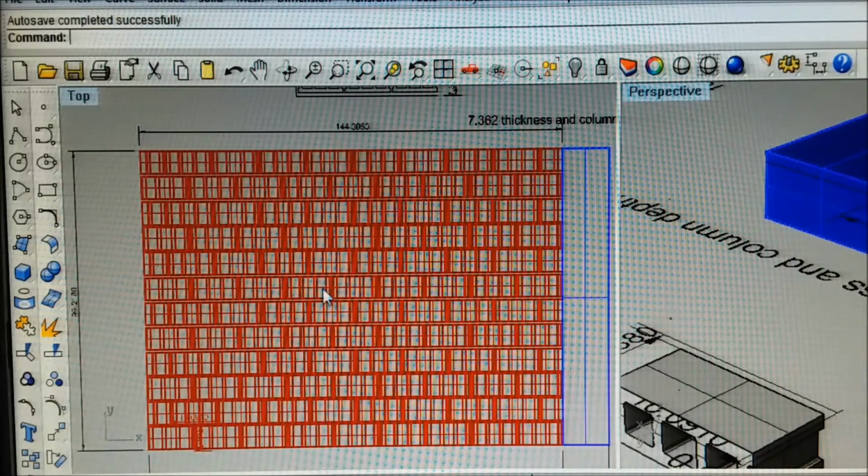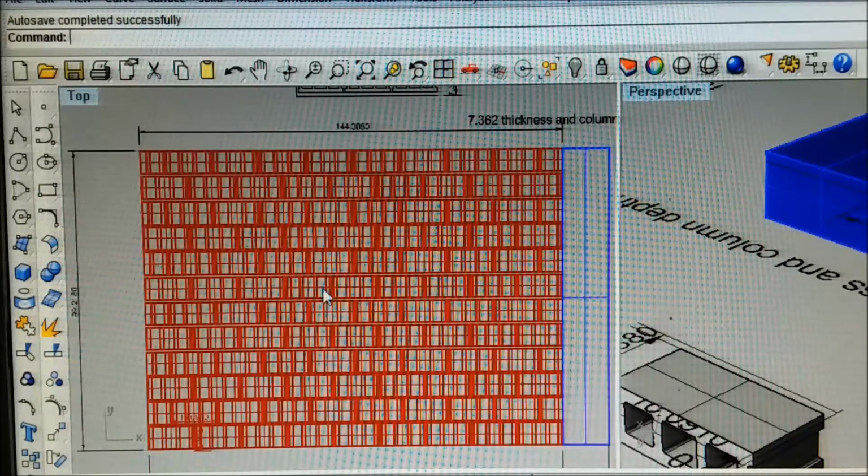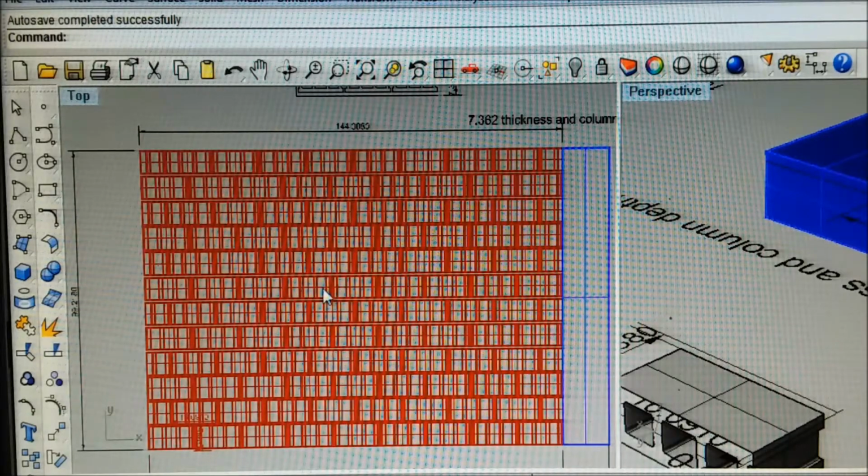The rebar, the reason it's really pretty much a price wash, is the hollow blocks have a horizontal rebar every 3 courses, and the vertical ones are every 3rd hole. Well, you skip a hole, and you have to overlap those pieces of bars by 16 bar diameters, so you lose that much off of every piece. And the length of the pieces they use is so that they can be standing on a scaffold and hoist the blocks up over it and lower it back down to where they're placing it. So with all that overlap, you lose an awful lot of bar.